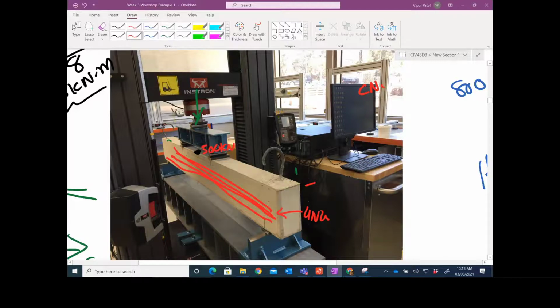Now it says that the bending moment in this region here is very small. Why do you need this extra bar going here? Right? You can cut it off. This is a curtailment. Why do you need the majority of the bar here, not in this region, because your bending moment is very small. So it says that you can cut it off.